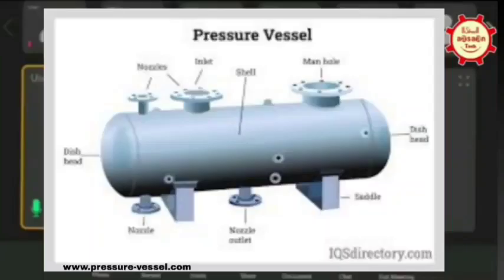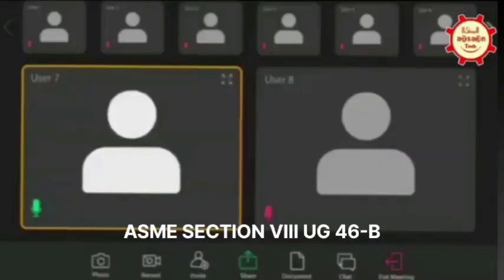Actually, as per our knowledge, it's the size of that equipment, where a hole is being made. So that hole would be within, meaning your vessel size should be a minimum of 10 feet. Then only can you make one hole in that. What if my vessel has only two openings, inlet and outlet, in that area? Yeah, that area. Atul, please repeat the clause. B, UG-46(b). Yeah, UG-46(b).